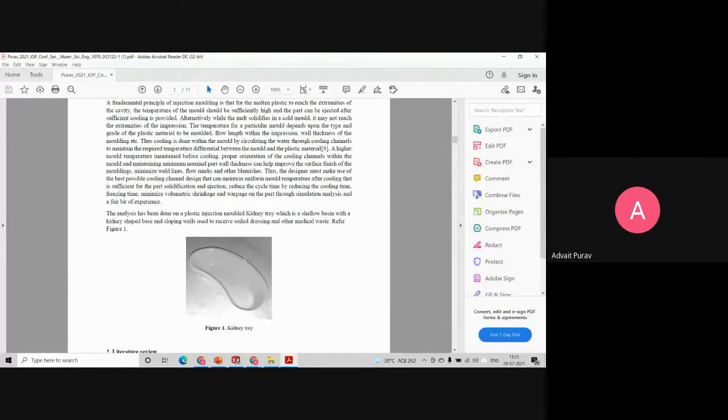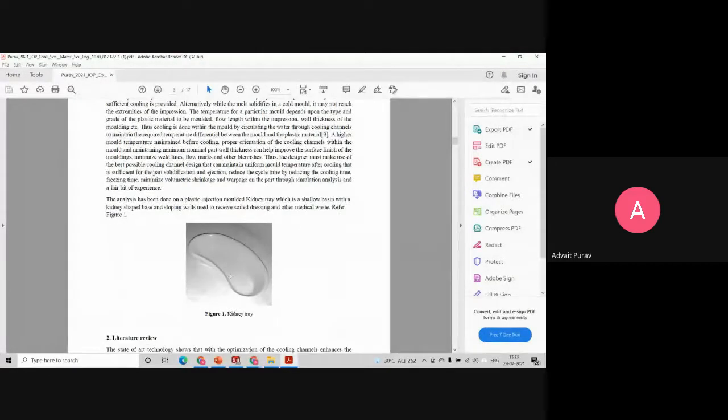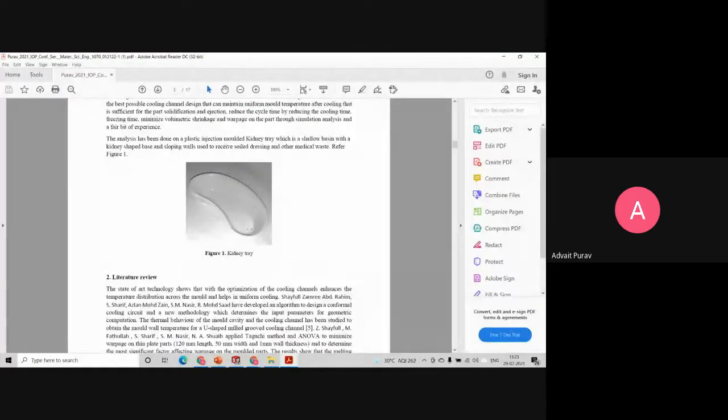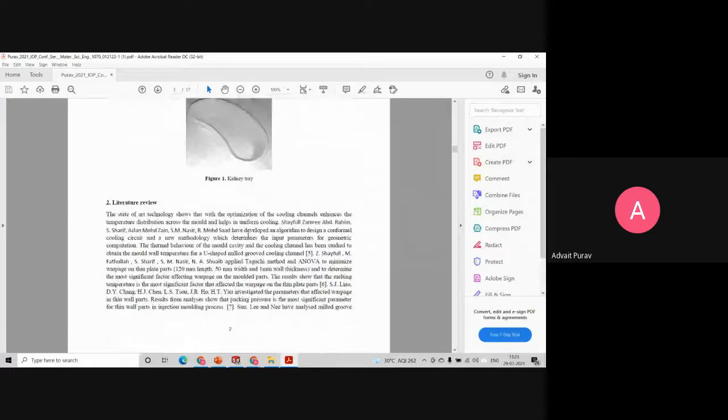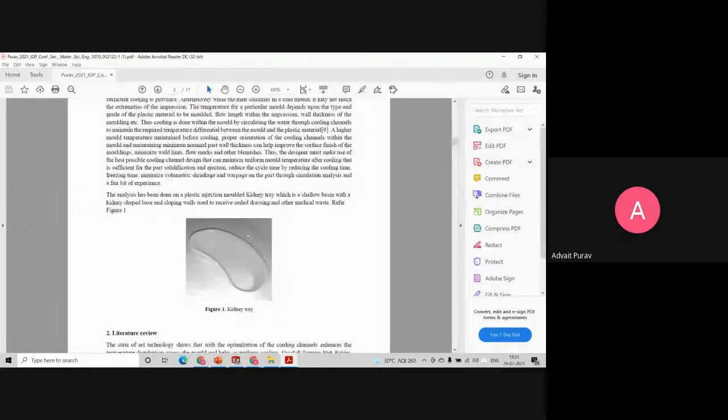इधर नॉन यूनिफॉर्म कूलिंग will be one of the greatest factors, because नीचे का जो वॉल थिकनेस है ना, ये पार्ट का नीचे का वॉल थिकनेस, inside the wall thickness is more and on the edges it's less. Okay, so for that on the edges वॉर्पेज उधर ज्यादा आता है जनरली. तो उसमें how you can reduce that particular warpage, ऐसा नहीं कि सिर्फ रिम्स पे आएगा, ओवरऑल भी आएगा, but how you can try and reduce that particular warpage was my particular problem statement.